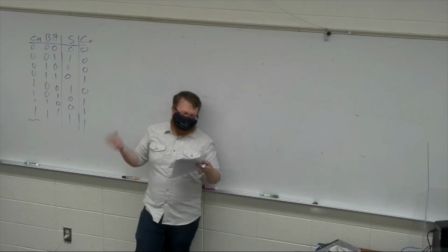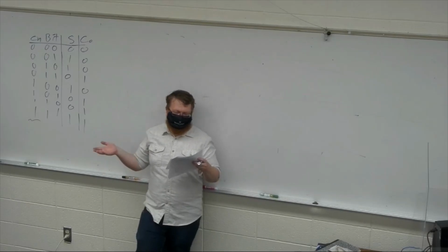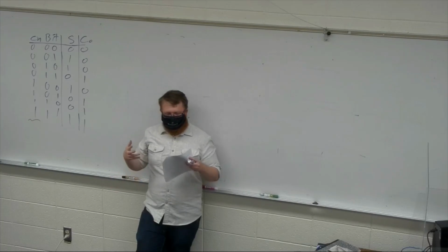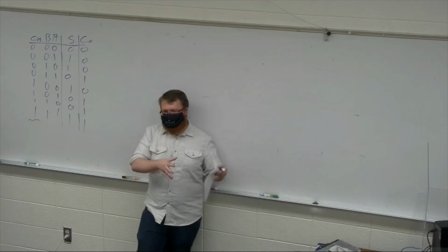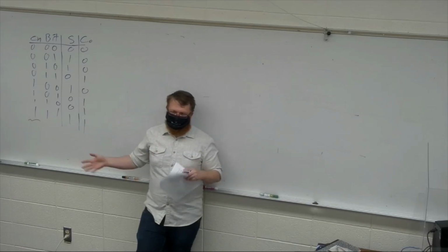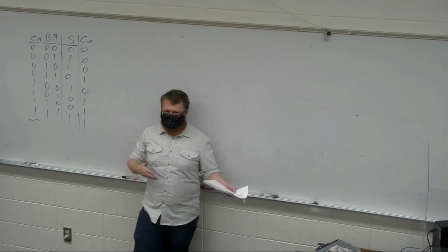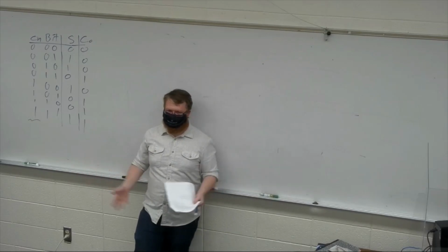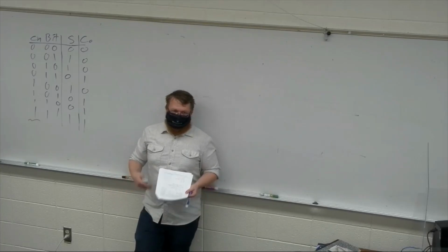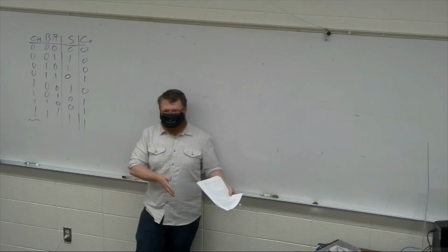Then D asks, if I ask you to change the design system using NOR gates, so instead of NAND using NOR, what simple change could you make at the first step, so at the K-map level, in order to change the design from NAND to NOR? And the answer is you just do product of sums instead of sum of products, because that conversion becomes really easy. I was sad to see nobody take a guess at that,